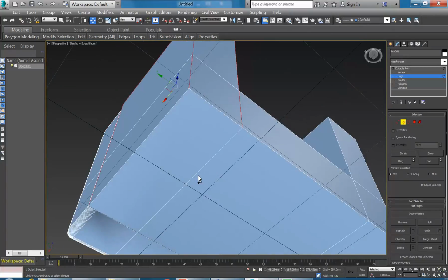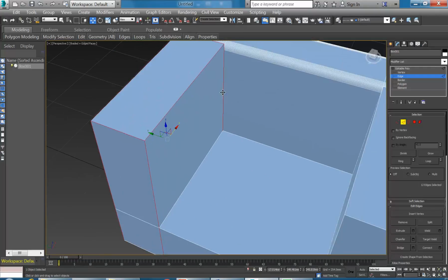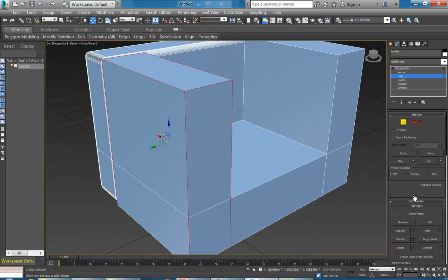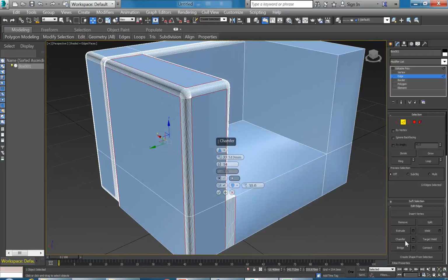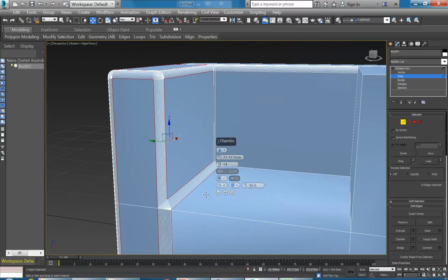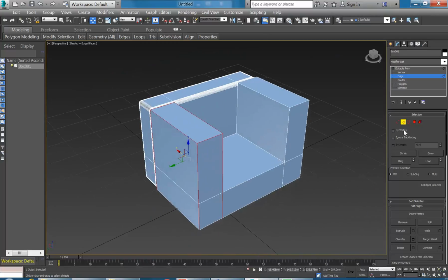Okay, so I've got these arms, which at the moment are connected to the base. So I can round them, but if I do, you can see there's a problem at the join there. So cancel out of that. I can just go to Polygon now, select those pieces,